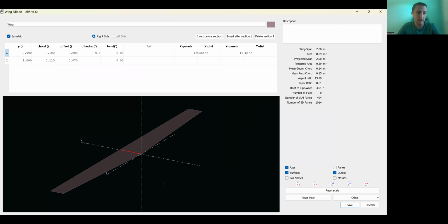You give your axis X and Y here and your Z axis, but our Y axis from 0 to 0.076 because the wing is 0.151. So that would be half of that, and it doesn't allow you to go any lower in accuracy here, so it has to be a 6. So we'll go with that.